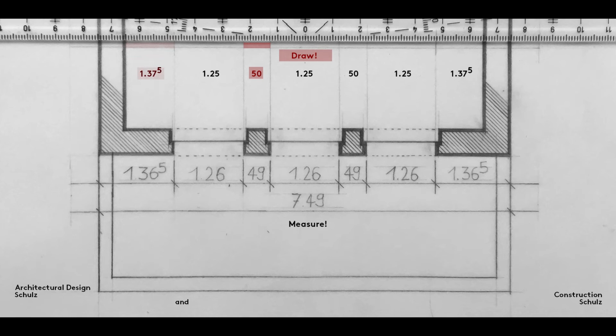You should always draw the modular dimensions, for example, walls 12.5, 25 or 50 cm thick, and door openings 1 meter wide, but label them with the working dimensions, that is to say 11.5, 24 or 49 cm and 1.01 meters.